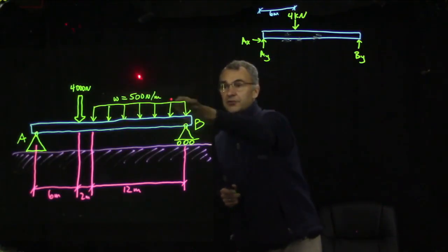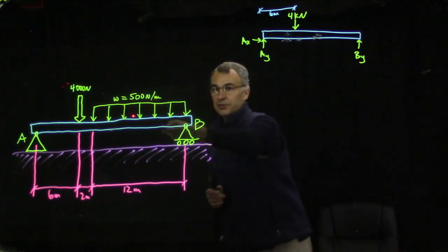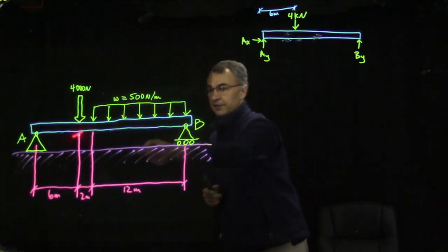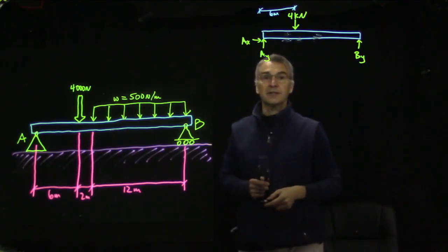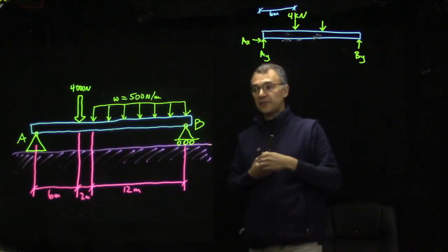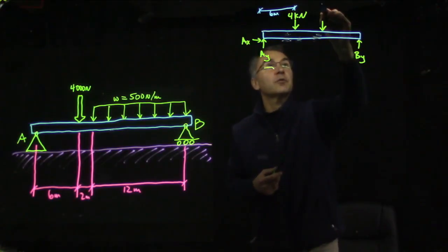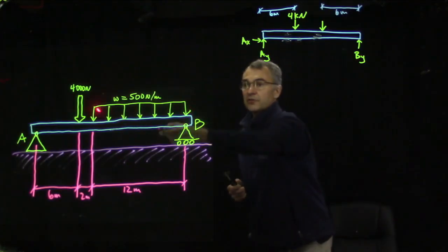And then we put that concentrated load at the centroid. Since this is a rectangular shape, the centroid is just the middle. So the centroid will be 6 meters back from the end, which will be 6, 7, 8 plus 6 is 14 meters over from the left. Let's write that down. So this equivalent concentrated load will go here. Here is 6 meters from the end, although I think we're going to want to measure things from the left end, but it seems like this must be 6 meters from B, since it's half of this 12-meter distance over which this distributed load is applied.